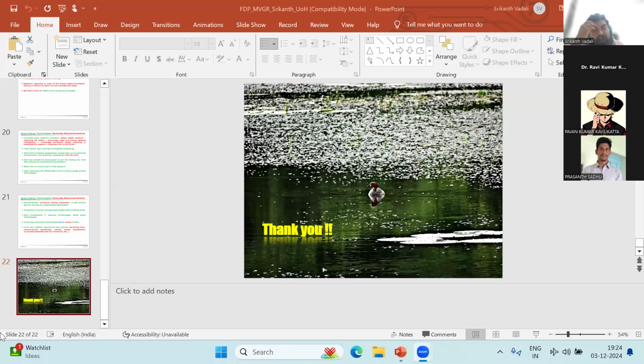I think simple thermodynamic softwares, FactSage, Thermo-Calc. These can be used, but you have to have appropriate databases because numerous databases will be there. For fatty acids, there must be a database, and then you know which is environmentally friendly. Then all the thermochemical data you should have in the database. Then the algorithm will collect the thermodynamic data and tell you the stability, right? Okay, Thermo-Calc and FactSage.